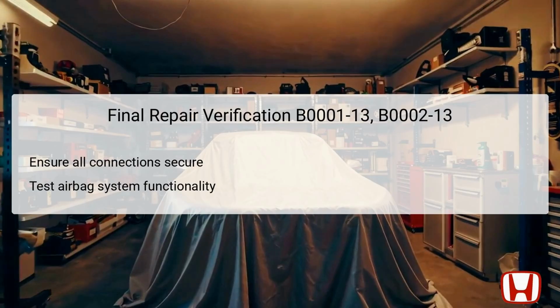After completing all troubleshooting steps, it is critical to carry out final repair verification for the DTC B0001-13 and B0002-13. This includes checking all connections to ensure that they are secure and properly installed without any frays or damage. Confirming that the driver's airbag inflator is correctly connected to the SRS harness and that all connections are intact is vital for the system's reactivity.